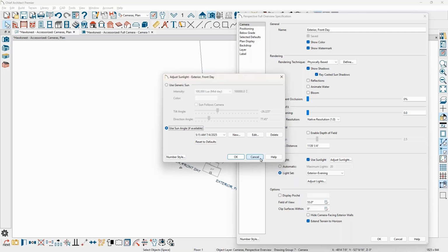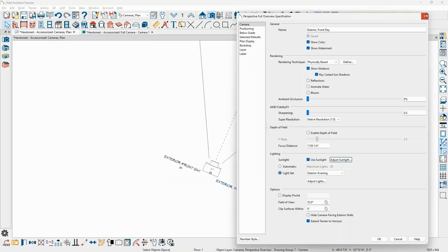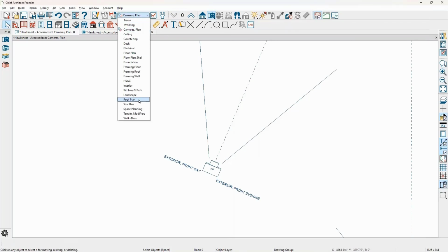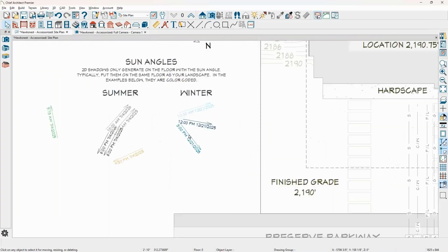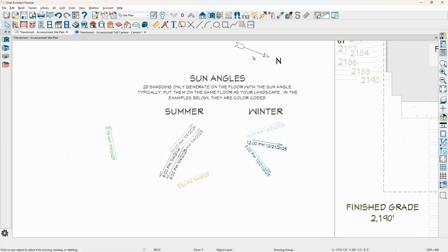Okay, good. So when you've set up your north pointer and your latitude and longitude, we know the coordinates of where your structure is, and assuming you've put that correctly on the plan, and I've done that down here, for the benefit of, let's go switch over to the site plan here. So I've done all these sun angles, right? And my north pointer is angled here. So when I run that time lapse, it's going to be using the coordinates, and if you started your time lapse at 10 a.m. and run it to 9 p.m., then it's going to be using that information.